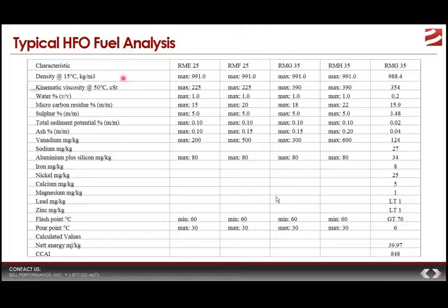And you can see that the density doesn't really differ unless you're talking about residual marine gas oil 35. But by and large, these are about the same. The kinematic viscosity, though, is different between RME 25 and, let's see, RMG 35.